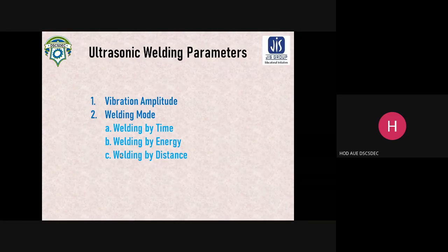That means if you provide the ultrasonic vibrations for a fixed amount of time, it will transfer a fixed amount of energy, and this fixed energy is enough to make the best joint. It is an assumption. It doesn't necessarily mean the material would be welded in the best quality.